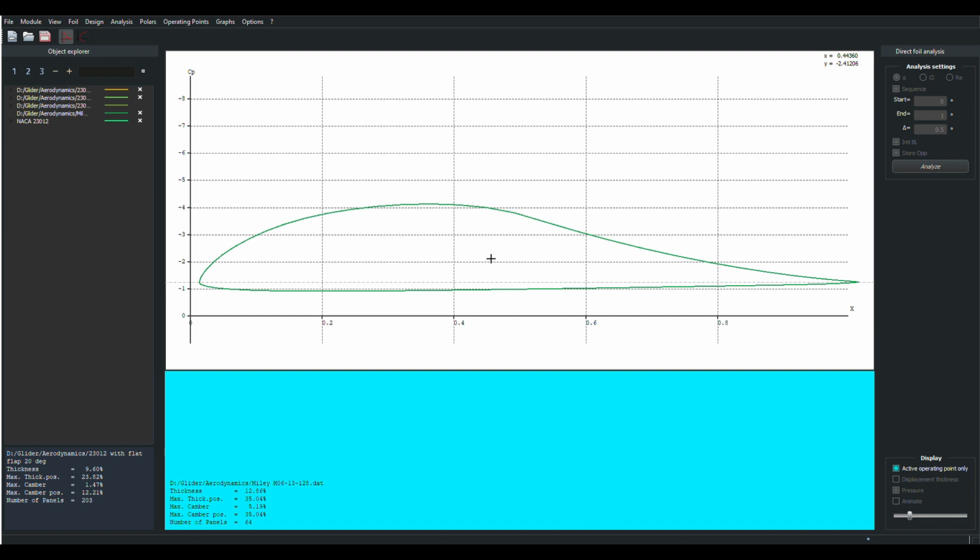However, I don't care about those numbers. I want to go 70 miles an hour, 80 miles an hour, 100 if I have to or want to. Well, you take this airfoil and you start going faster than about 45 miles an hour at the Reynolds numbers that we're operating at, and the flow is just going to go whoop, right off the back, and you're going to have separated flow, and you're going to have all this turbulence back here, and you got massive drag. This airfoil is not designed to go really fast. It's a floater, as we say in the sailplane business.